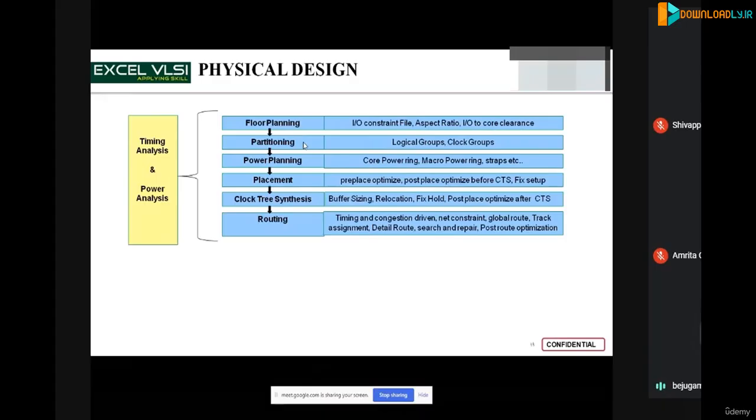So now I have done the placement of cells. I have just propagated the clock. I did not do any interconnects between the cells. So I just placed the cells, I gave the clock propagation, and I did not give any interconnects. So routing is a stage where you give the interconnect, I mean to say that you give a logic interconnectivity according to the gate level netlist. So whatever nets, whatever interconnect information that you have got in the gate level netlist are physically routed, that means physically connected from one logic to another logic.